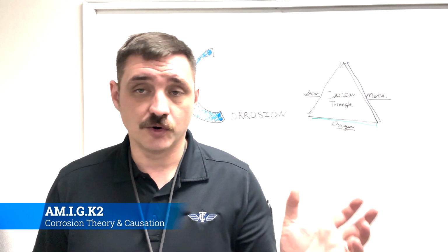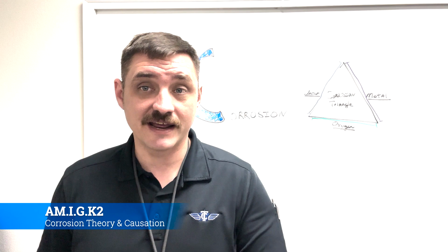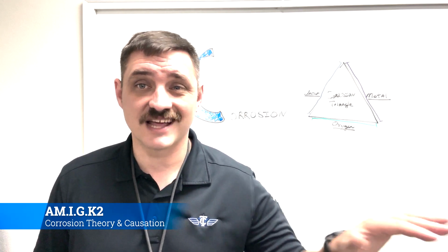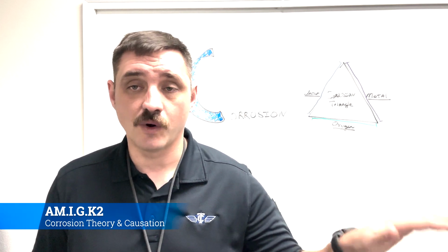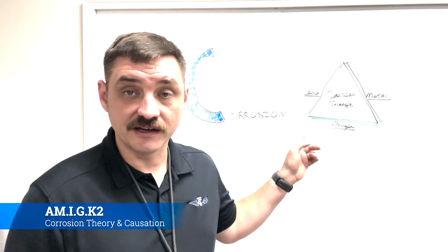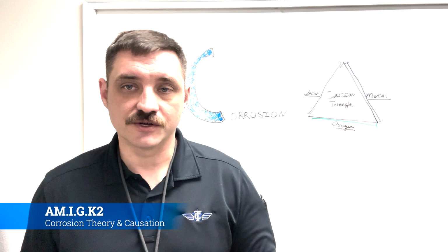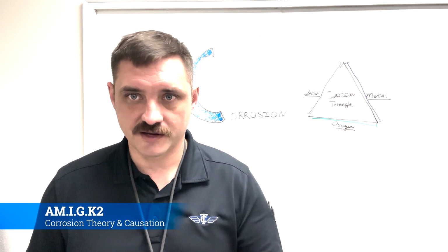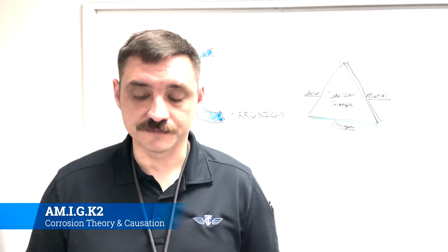The same idea with the old boneyards, that we can mitigate this risk if we park them someplace that doesn't have a lot of oxygen or doesn't have a lot of water in the air, which will slow the corrosive process down, because we're taking a leg of the corrosion triangle out. So the area that it's in can be very, very important.